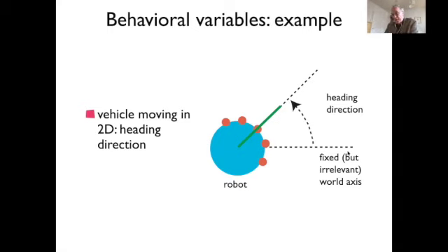It will turn out that for the behavioral dynamics to work that we'll look at later, you don't actually have to know the heading, you only have to know differences in heading. Conceptually, it's still important to think of this as something that's fixed in the world. Differences in heading make direct sense. You can turn by giving different speeds to the left and right motor. You can compute how much, depending on how large the wheels are, how far they are from each other. And actually, these two are enough to determine how much difference in turning rate of the wheels leads to change of heading.